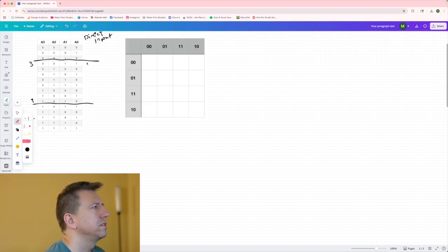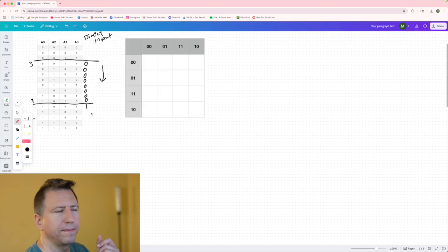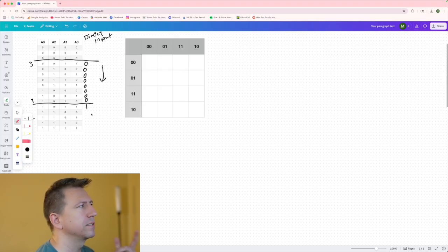So while we're inside the count that we want to be in, this should not be activated. And as we're counting up in number, we want to keep it inactive all the way through number 9. But then at number 10, so right when it turns into 10, we want to immediately activate it, and so we'll go back to the number 3, okay?